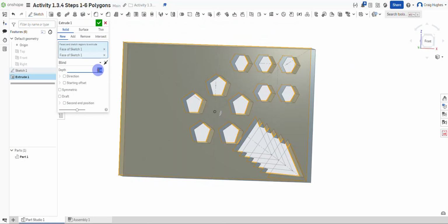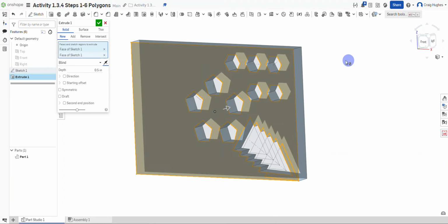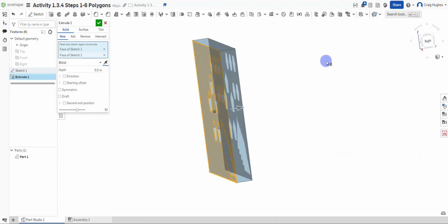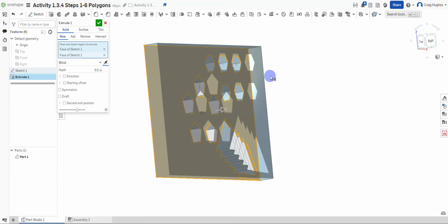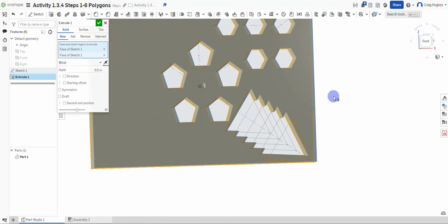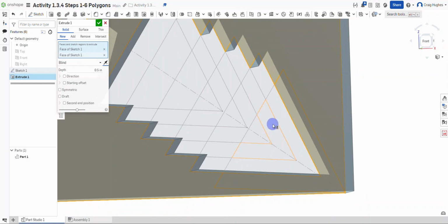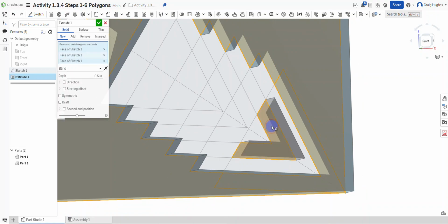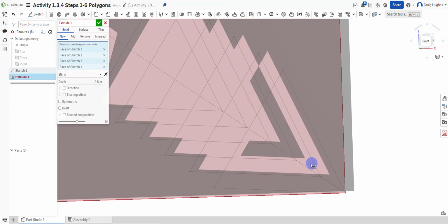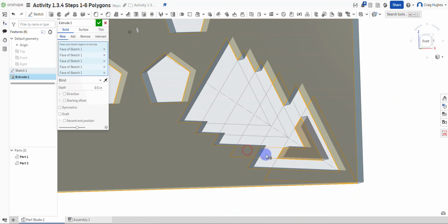We're only going to make this about a 1/2 inch, and we do want to flip the direction, so that the sketch is on the front face, the orange sketch, and we're going back. We're going to end up adding to this sketch in a little bit. Now as far as finishing out the plate, we might have to see how it looks. I'm going to pick right in this portion, maybe here, and sometimes it may give us just a little bit of an issue.